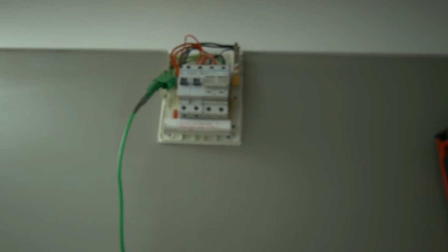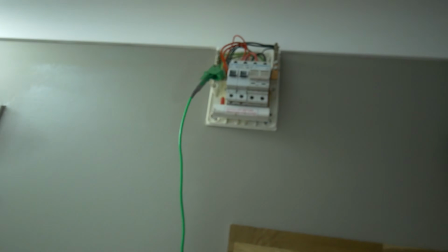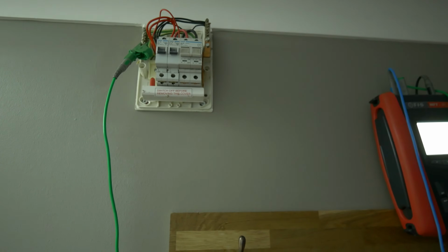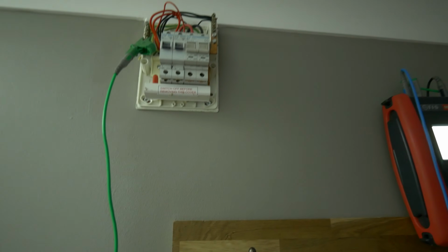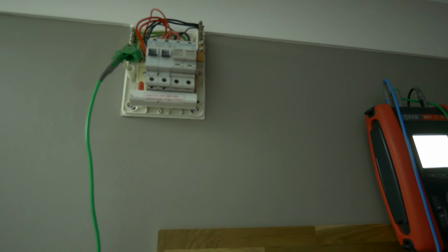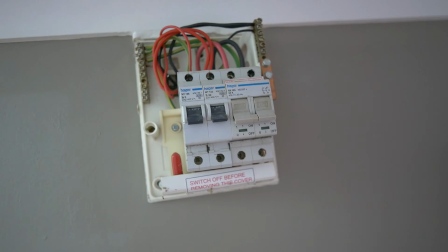When you were doing a ZE at the main point of the distribution board, you would disconnect the earthing conductor, but in this case, because it's a ZdB, basically a ZS at a consumer unit or a distribution board that's remote from the intake, like your first distribution board if you like, then you need to make sure you do that with those parallel paths in place, and we call it ZdB. So we've got the power off now, and you can see inside that consumer unit my suspicions were correct.